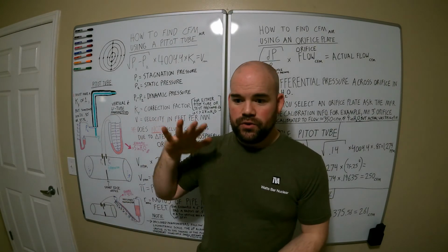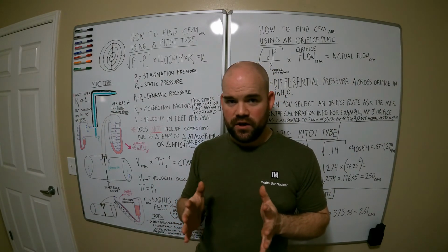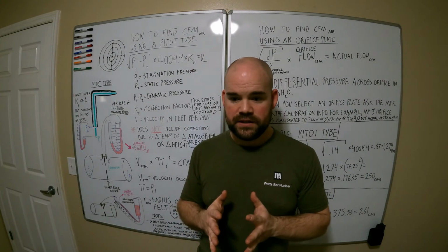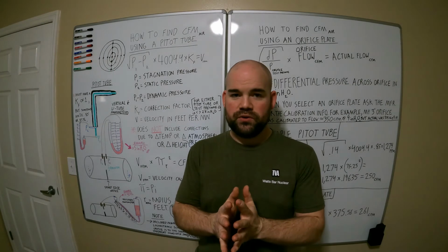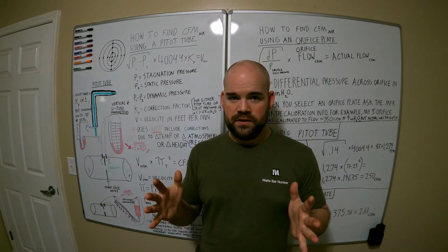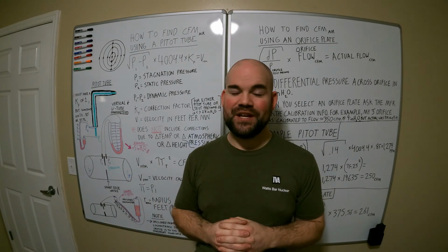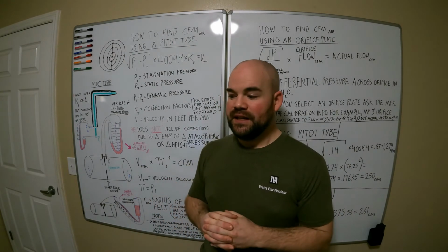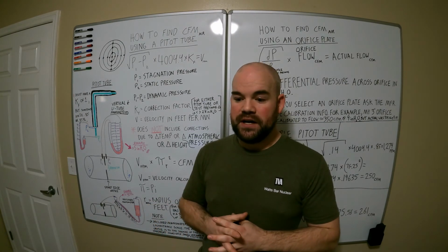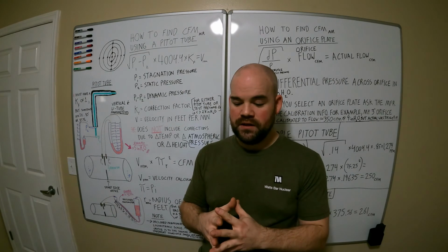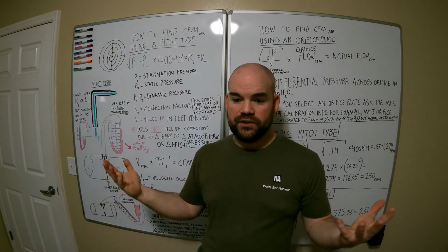So as you cram more oxygen tighter to occupy a smaller space, you're also increasing temperature. Temperature makes molecules want to move away from themselves, okay? But we're not wanting that. We want the air molecules to stay tightly close, all right? And that's why we mix more fuel and make more power. If temperature rise exceeds too much, then the efficiency of your supercharger is terrible and you actually lose density in your air.